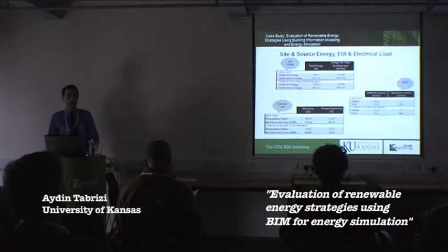Our source energy has basically increased from the base case to current performance, and electrical load generation by the PV panels has decreased. But for the energy use intensity for our equipment, basically lighting and HVAC, there has been no change, since the current performance and base case work non-stop, on weekends and weekdays.